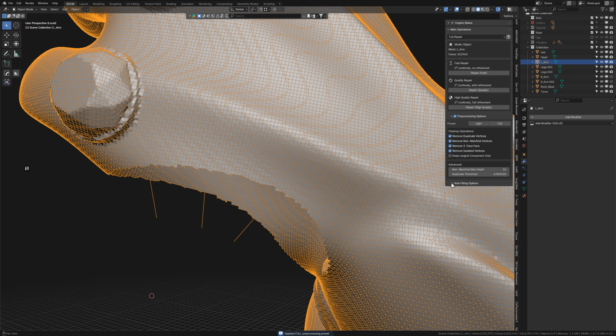And in the hole filling option, you're gonna wanna set this to max value, which is 100,000. Anything lower than this might require more fiddling, so make this 100,000. And the max diameter ratio is what it requires to fill the hole with. Usually when this value is lower, it will clean the mesh from the non-manifold vertices, but it will not patch the hole. So let's see this.